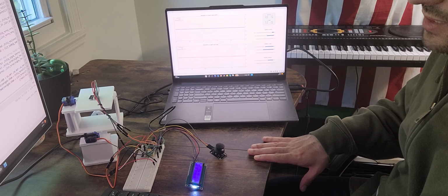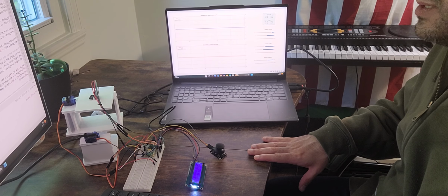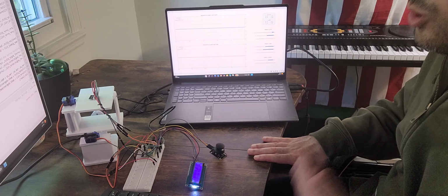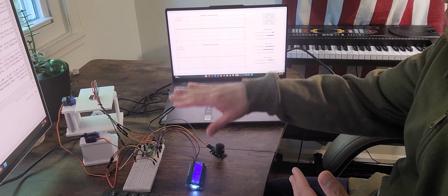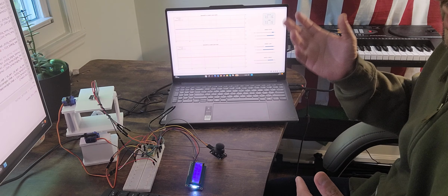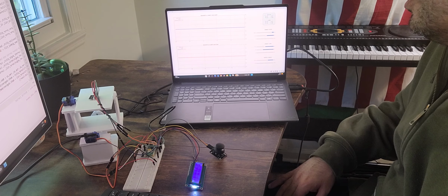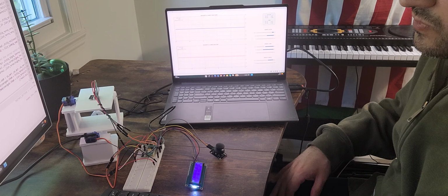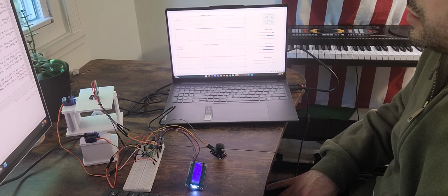Or it doesn't have to be a deck; it can also be like a satellite dish platform. Of course, you would need to add a third yaw axis for that. Right now, it has two axes, pitch and roll, but for that kind of application, you also need a yaw axis and probably one more sensor as well.